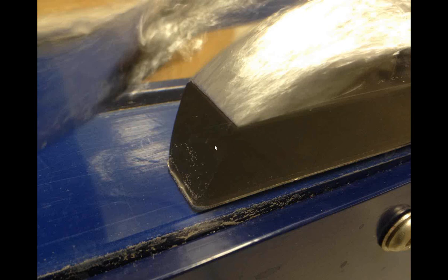So this is a close-up picture of Isco's low diameter, low profile area velocity flow sensor. This is a close-up picture of it because keep in mind the sensor that you're looking at is only 3/4 of an inch tall. But this is in a plexiglass flow chamber in a hydraulics lab at a local university here, which gave them the ability to easily adjust the slope of the sensor and how much water was coming down that. So this is what you'd be looking at if you were able to actually see your sensor in the pipe in high velocities and with something like 1.5 inch of water coming down at it.